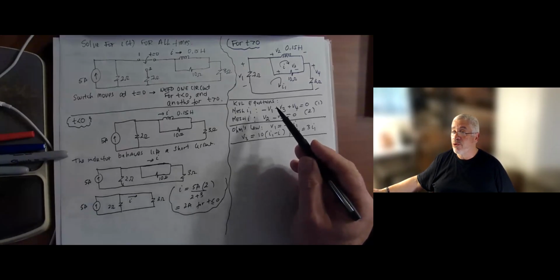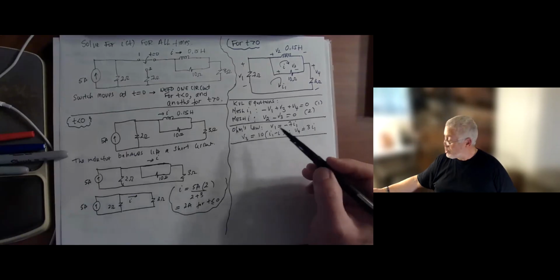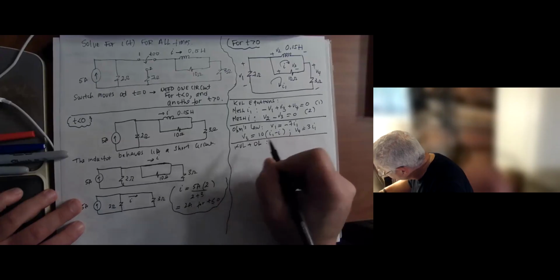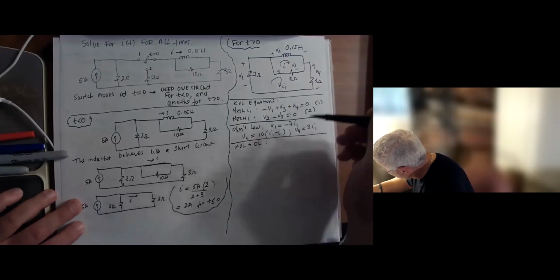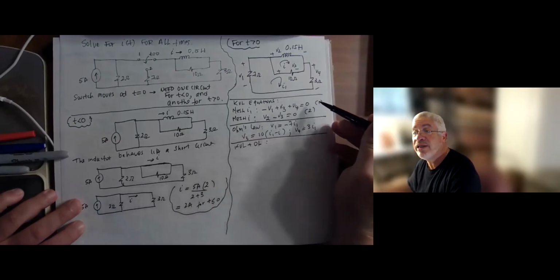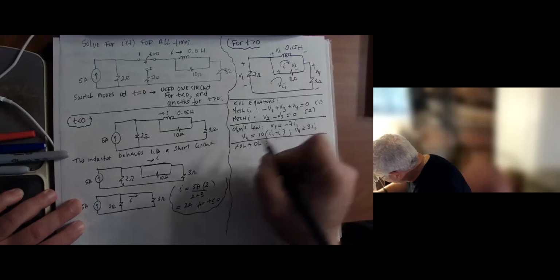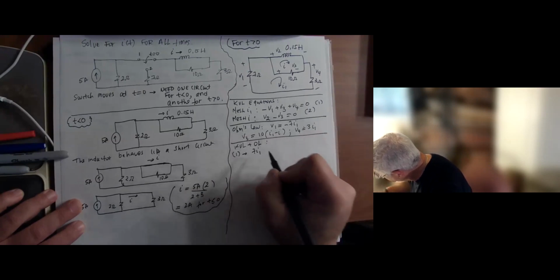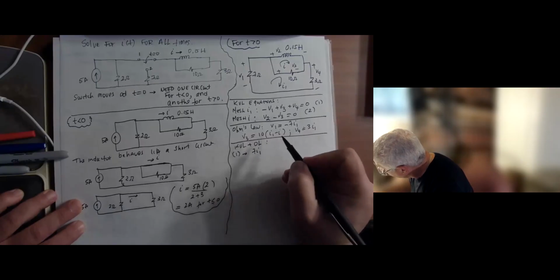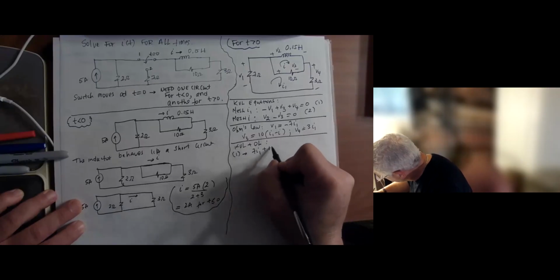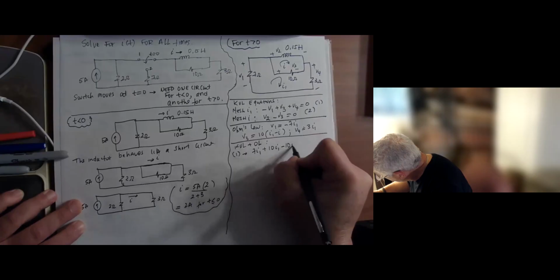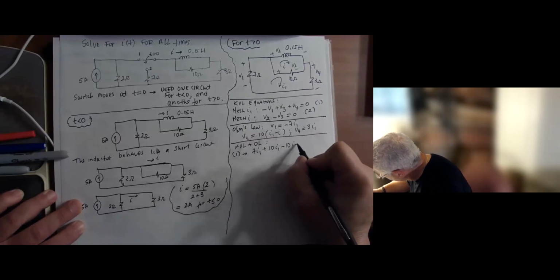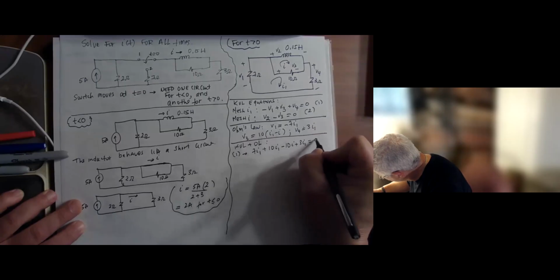we don't have source equations here. Then we do Ohm's law. I want you to put the Ohm's law. So this step will be KVL plus Ohm's law. I'm going to basically put this Ohm's law into the KVL. I'm not touching the inductor yet. So equation 1 becomes minus V1, so 7I1, plus V3, plus 10I1 minus 10I, plus V4, plus 3I1 equals 0.